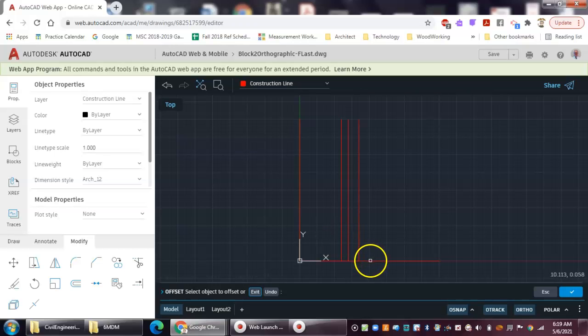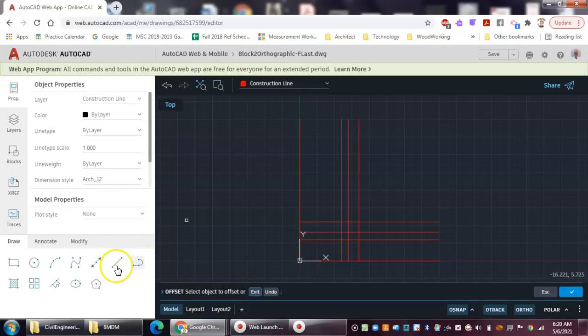Now I'm going to offset this line for my height, and my height is 3 inches. So I have to keep the same spacing between views. So this is going to be 1 inch, enter. And then again, my depth will be 1.5 inches there. Okay, so I've got 8 of the 9 lines taken care of. Now I need to add that 9th line.